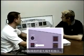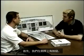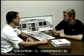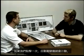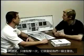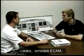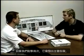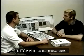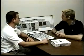Explain to me side stick priority and the indications. Okay, first of all, we've got the button on the side stick. If we click it one time and the autopilot's engaged, it'll disconnect the autopilot. The problem with just clicking it one time is it'll give us the master caution, an aural warning, and an ECAM. If we click it twice, though, it will give us the master caution sound, but the ECAM won't come up and remain up there. It automatically clears that ECAM.